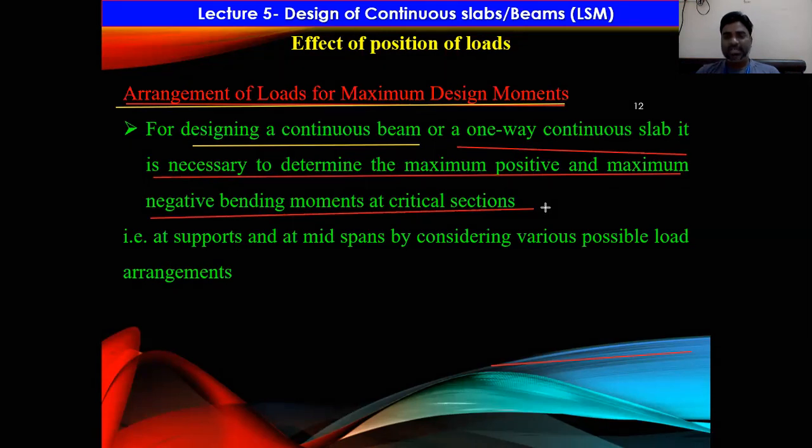right? Wherever the critical sections are, at the critical section, you need to determine the maximum positive and maximum negative bending moments and shear force at supports and midspan, that is, by considering the various possible load arrangements.